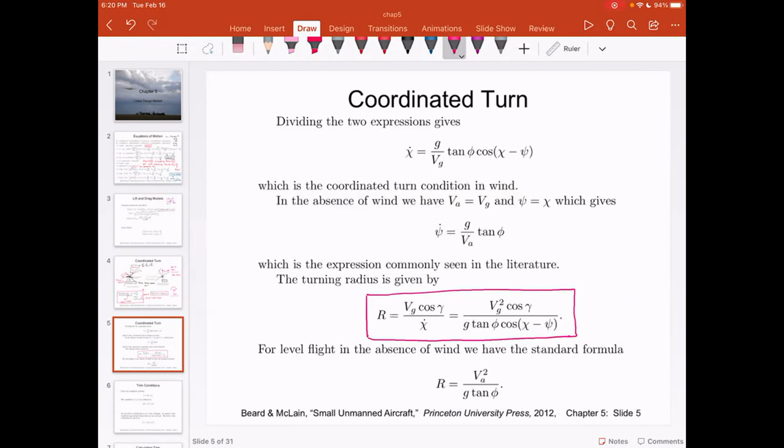And this equation will be useful when we try to look at or simulate the turning dynamics of a UAV. So please note, unlike cars, UAVs don't turn at their current location. There is a difference between turning of planes and turning of ground vehicles or, say, cars.